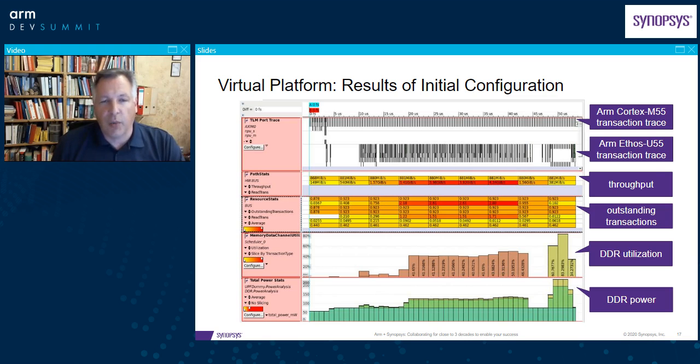These darker bars are the read accesses, which go up while the U55 is reading data, and afterwards it's writing back the results. And you see that clearly. What you see on the very bottom is that you can visualize the power and performance data side by side. So you can do a combined performance and power analysis and optimization of such systems.